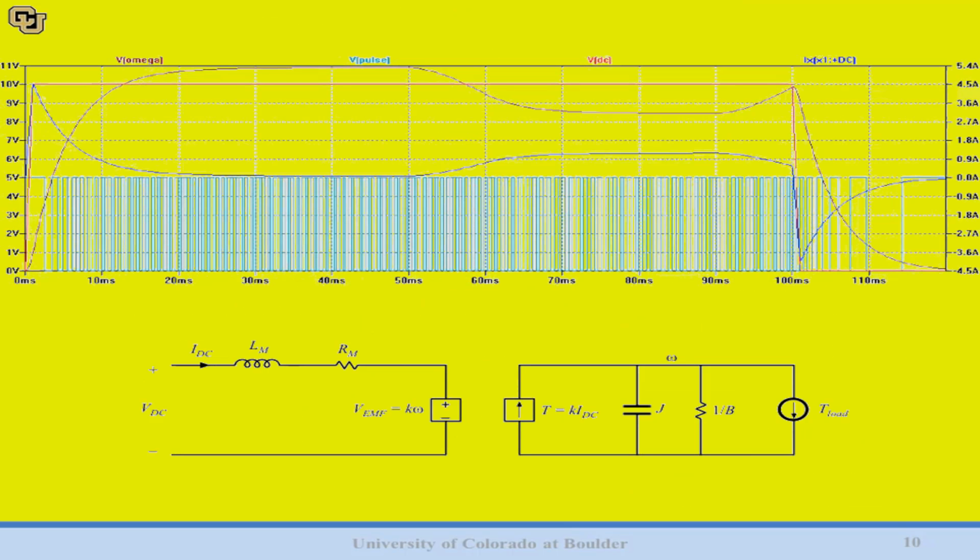And if you were to do that, you might get a plot like this. You see we have V omega. It thinks it's a voltage, but really we know it's an angular frequency, so make sure you scale accordingly. And there we have our turn on transient and turn off. You can see our encoder pulses in kind of teal down here are nicely generated from that separate block. And we have things like our motor current, the DC input voltage, and encoder pulses.